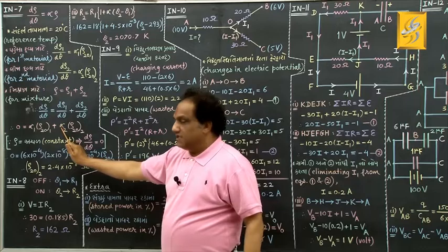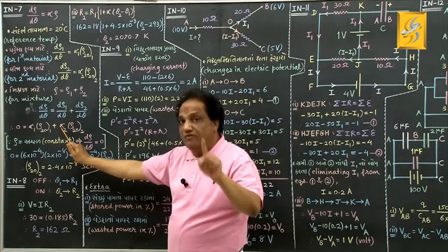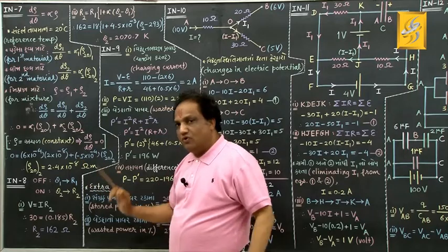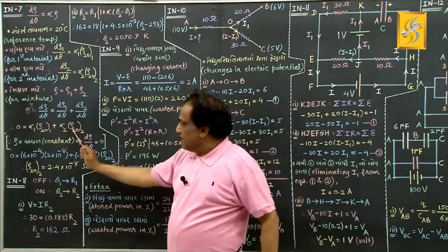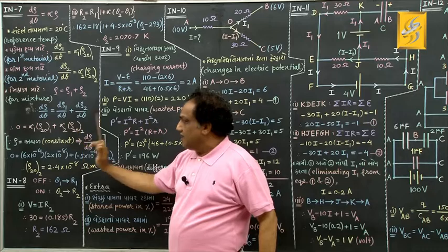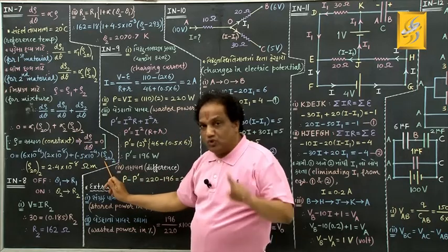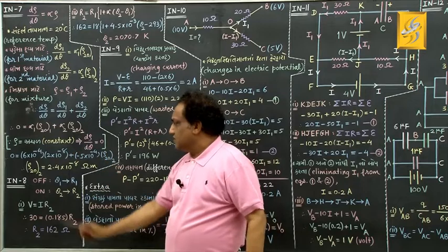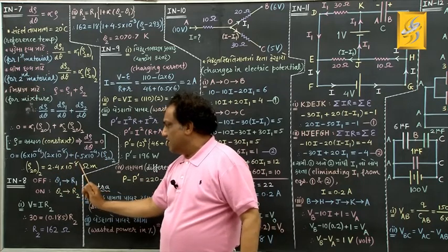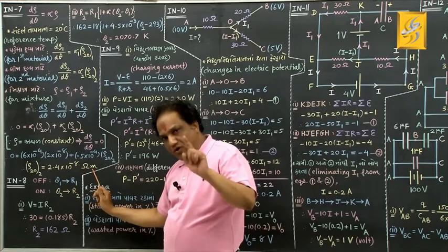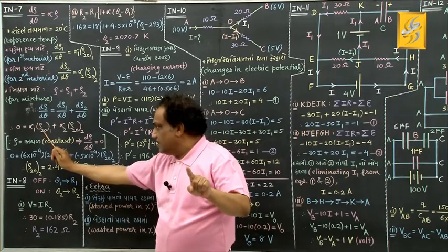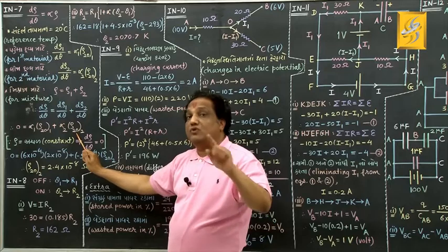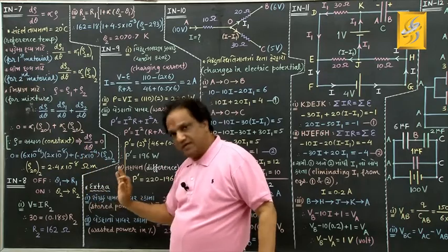And then this is the temperature coefficient of resistivity for the second material which they have given, minus 5 into 10 raised to minus 4 degree centigrade inverse. And this is the resistivity of the second material at 20 degree centigrade temperature which we are supposed to find out. Just simplify, you will get this value, 2.4 into 10 raised to minus 8 ohm meter, correct. Because the unit of resistivity for the first material was ohm meter, naturally this resistivity will also have the same unit, ohm meter, correct.